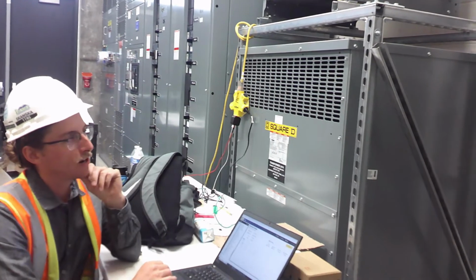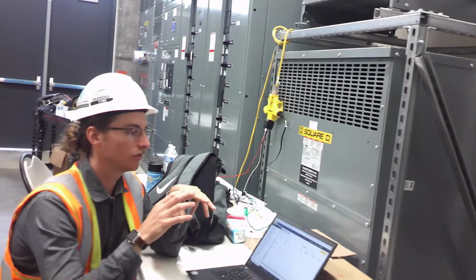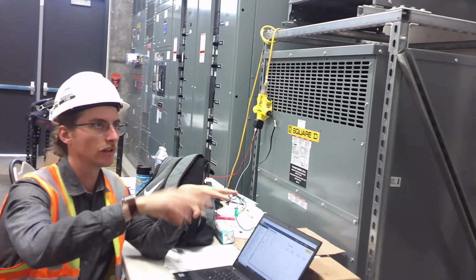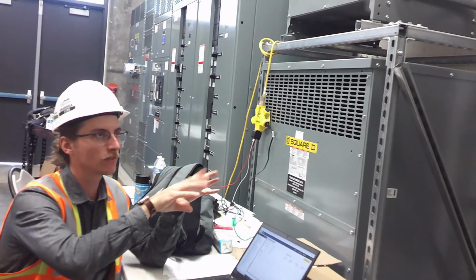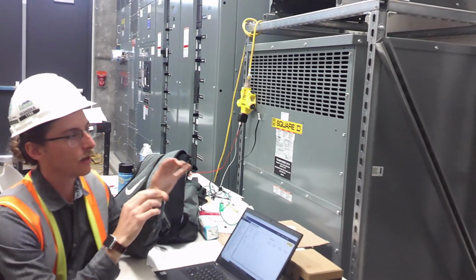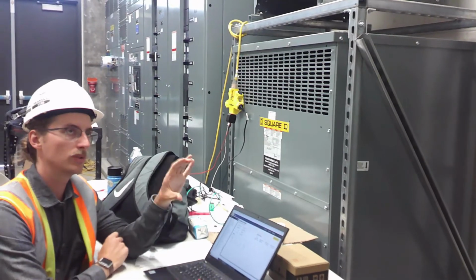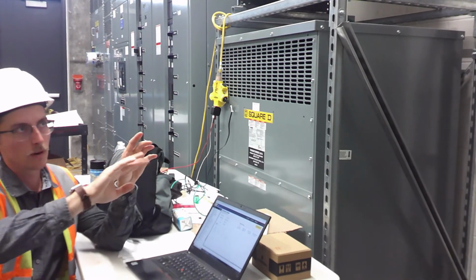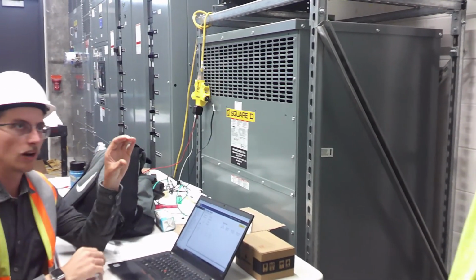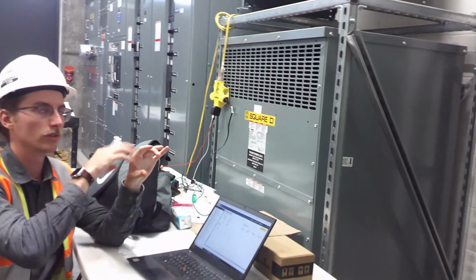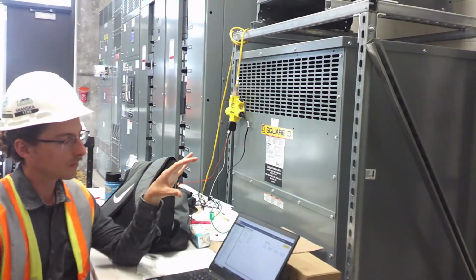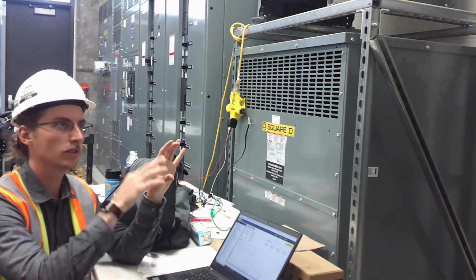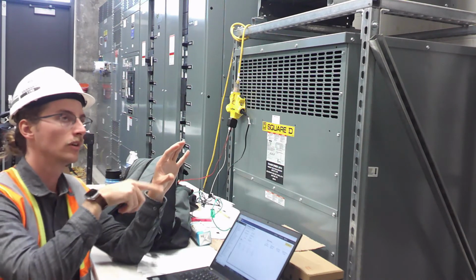So one thing I didn't cover in the PowerPoint, there's a bunch of individual restrooms. You've got the girls and boys, and then there's like a small restroom in the middle of them. Those are using an aux sensor that's built into a switch. And the way that works, there's no digital one button or anything. It's just an aux sensor that's wired back to the controller, similar to the ones on the ceiling. And so you don't actually see it as a switch through the system because it's wired in as an occupancy sensor.